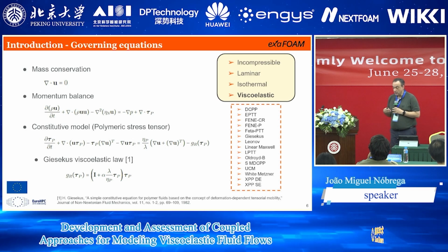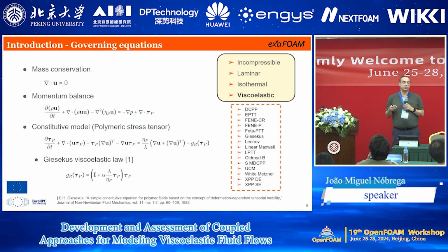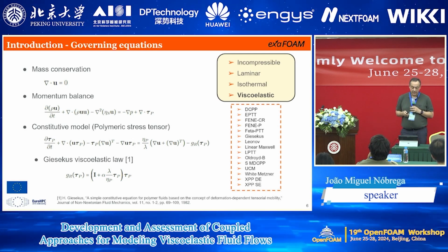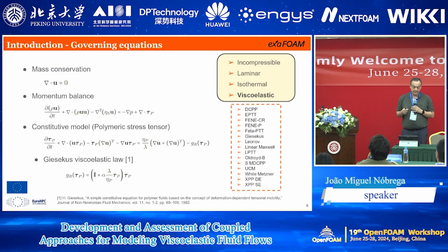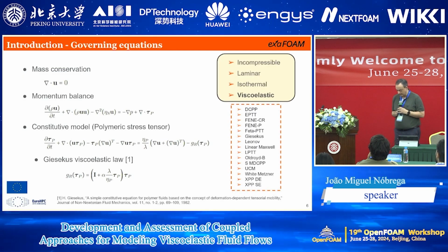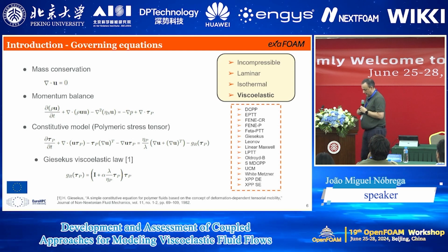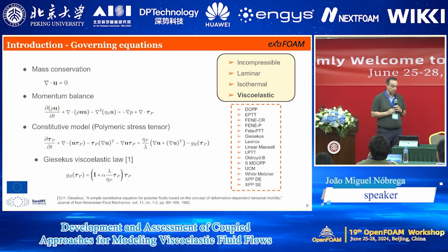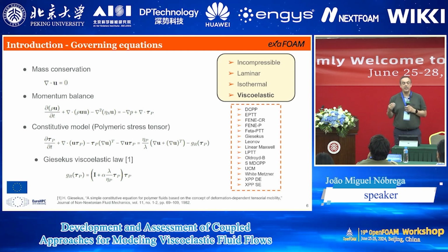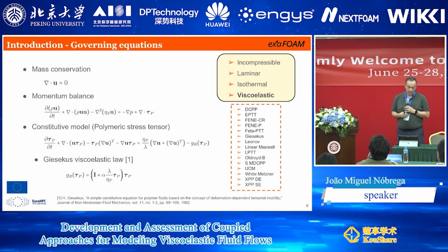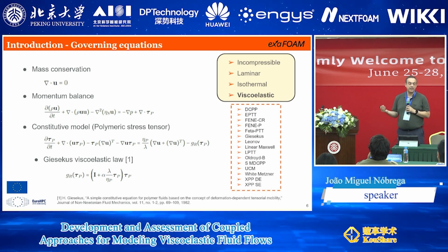And in the usual approach, these equations are solved in a segregated manner. And what we aimed at in the Exafoam project was to test what would happen if we solve the problem coupled. We try to couple the different equations.